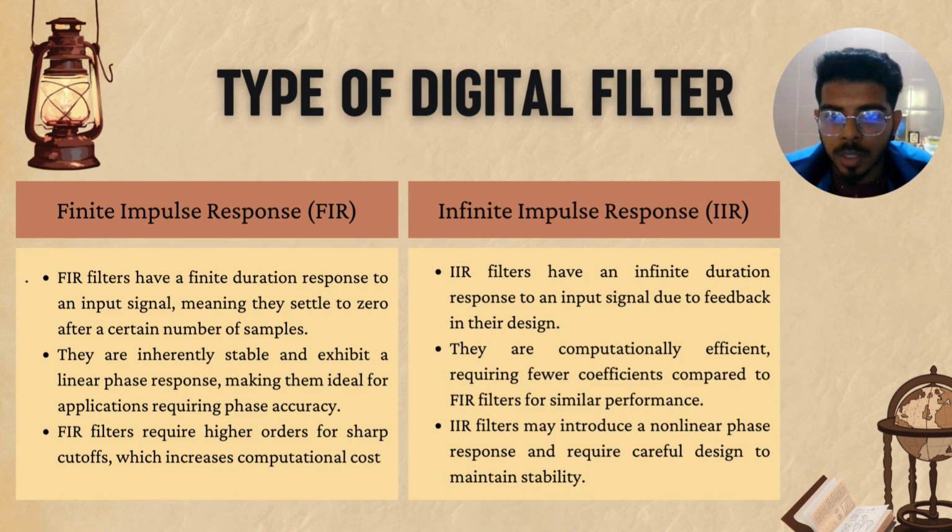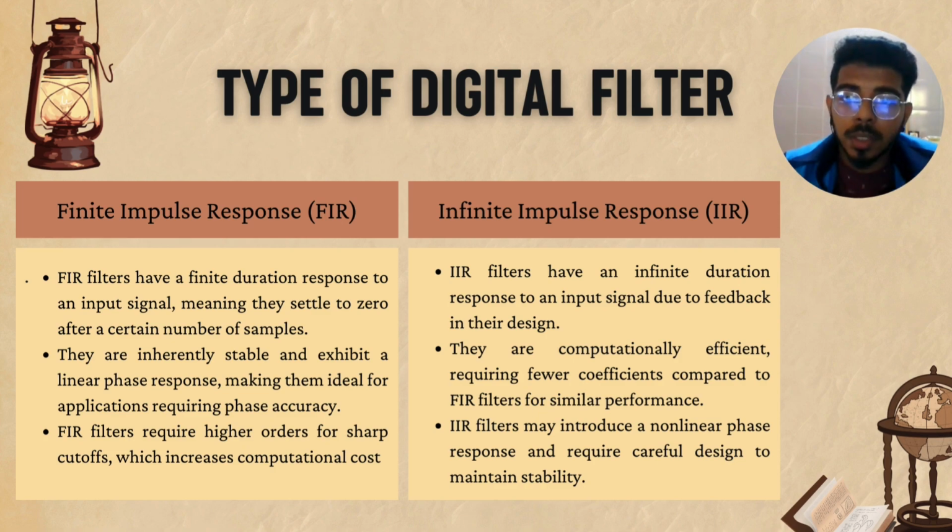Okay, here we are having two digital filters, which are finite impulse response, which is FIR, and infinite impulse response, which is IIR. So FIR filters have a finite duration response to an input signal, meaning they settle to zero after a certain number of samples.